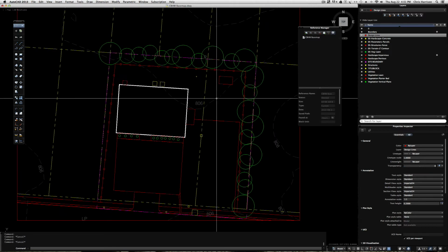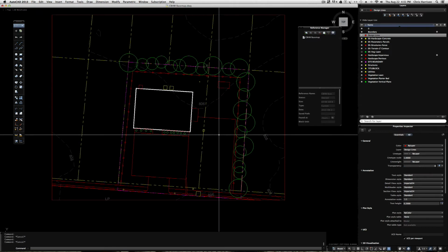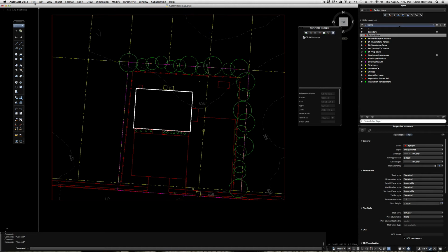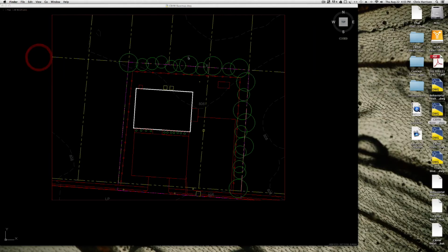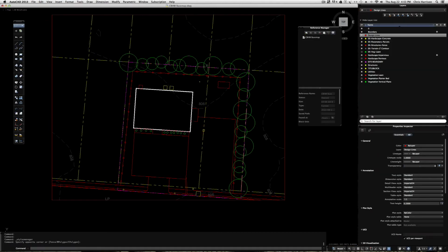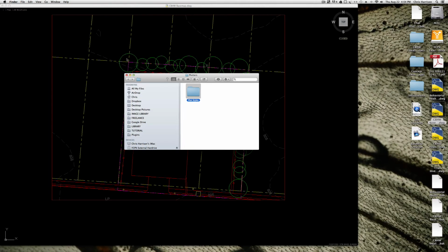You can copy these colors that I have it at now to help everything read so everybody's base map will be consistent. The way the color ramp works, and I told you we had pen settings, the LDI, or you guys are using the Sasaki pen settings that you should have installed, and I should show you how to do that. You would go to, okay, so in Mac, I'm going to go to my file, plot styles. And this might be a little bit different on the PC, so we'll have to navigate through that, but I can walk you through that.